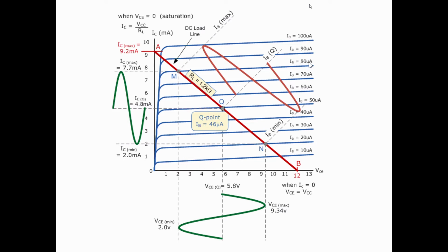So it will tell me that 80 microamp of base current will give me almost 7.7 milliamp of collector current. The manufacturer already tells me this. I have to have this characteristic. Correct? That's the step. That's point number 1.